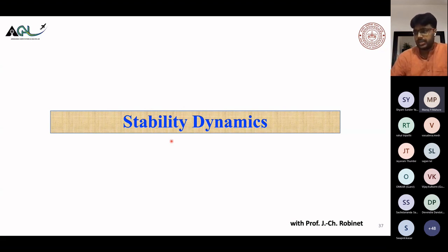Just to go back to the history a little bit on this. This approach has been developed to study how a flow becomes transitional from a purely laminar or stable flow. If you have a stable flow and you increase the Reynolds number, first the symmetry will break, then it will become periodic, then it will have more frequencies, like a multi-periodic system. Then it will become aperiodic, meaning it is no longer periodic, and several frequencies are present. And then it becomes transitional and then turbulent.